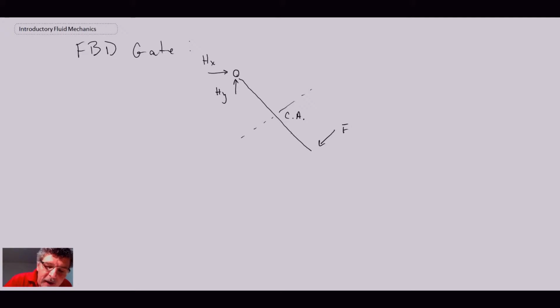And we also have, yet to be determined, the center of pressure. That is where the force due to the fluid is acting, and we call that force FR. I'm drawing it normal, going outwards, and so that is the free body diagram. XCP we have not yet determined, but that would be XCP, YCP for the center of pressure.